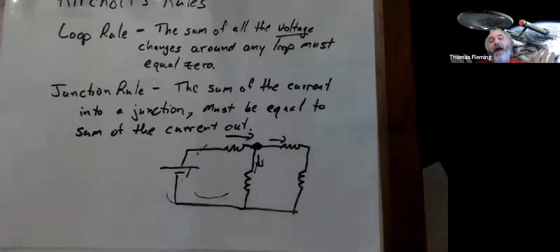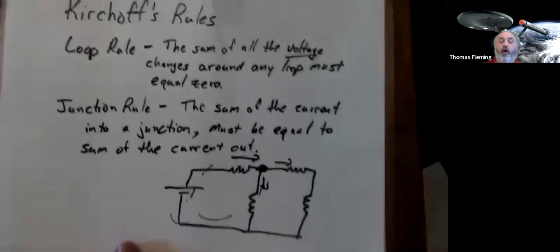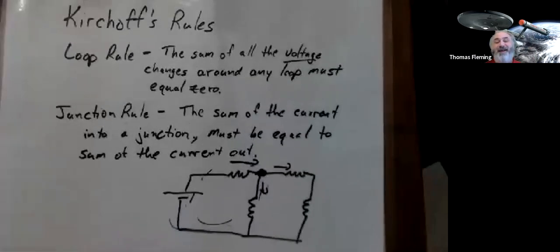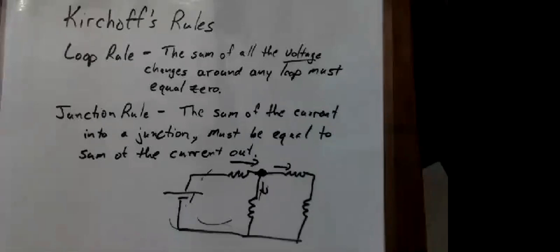So no matter how complicated the circuit, no matter what path your electrons take, the total drops in voltage have to equal whatever voltage I started with. They always balance out to 0. Those are Kirchhoff's rules. And we've been secretly using Kirchhoff's rules for a while now.